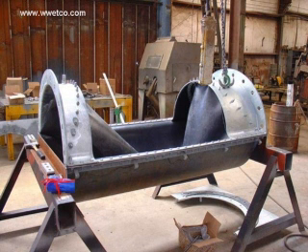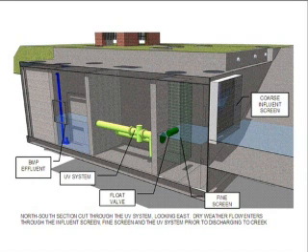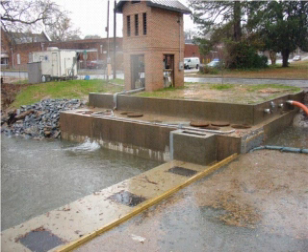There are 6 34-inch diameter openings, pipes that go through that structure. And inside that structure, there's a bladder that pretty much seals off that flow. One of these actually allows flow to go underneath the bladder. All these bladders are on a seat that seals the flow. There is water on top of the bladder that's contained in that structure, and it is to a level about the top of that, or near 6 inches below the top of that weir. In other words, if the rainfall occurs, the water level on the upstream side would have to get higher than the water inside on top of the bladder. That differential head then opens the bladder and lets the flow go by.